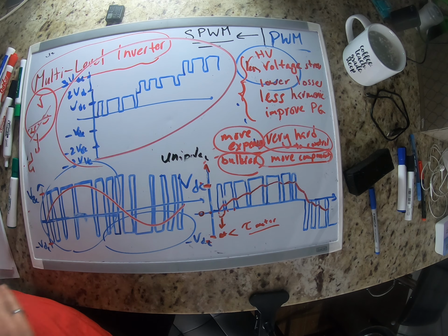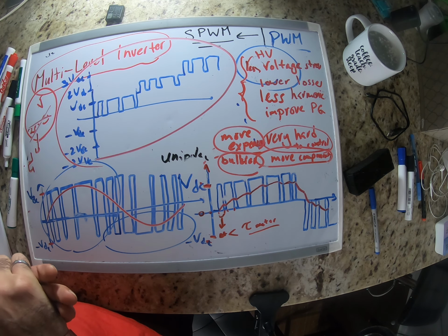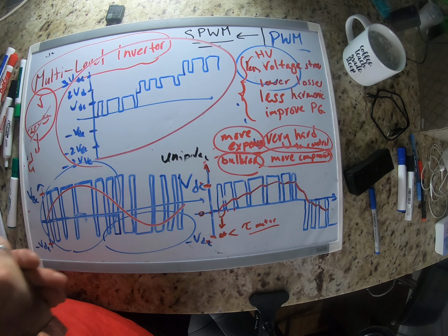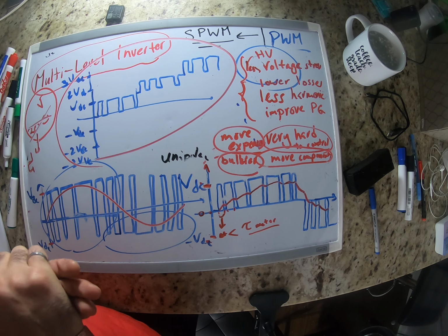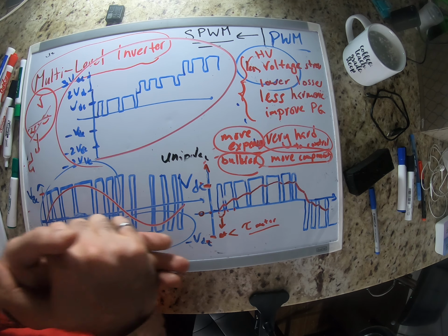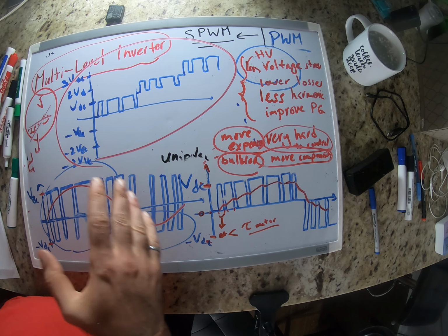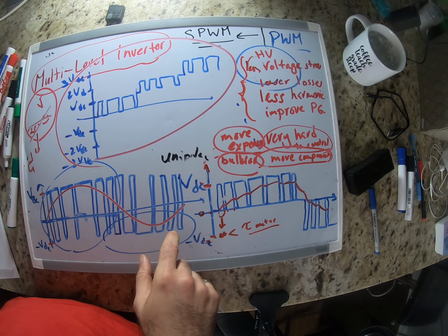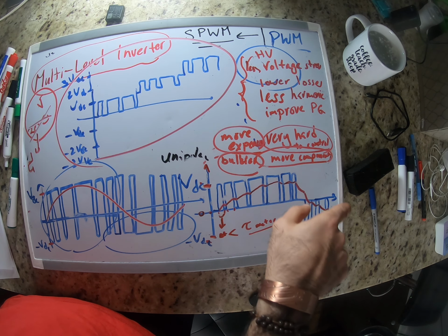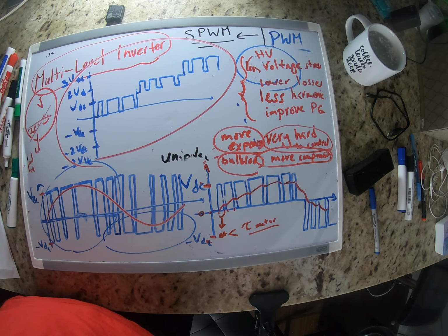If you just watch the video, it's not going to be that effective. If you just read the textbook, it's not going to be that effective. One thing that would definitely help you is to do it yourself once or twice. Try to do it at least for one unipolar and bipolar once, and try to see how you're basically creating these voltages using PWM.